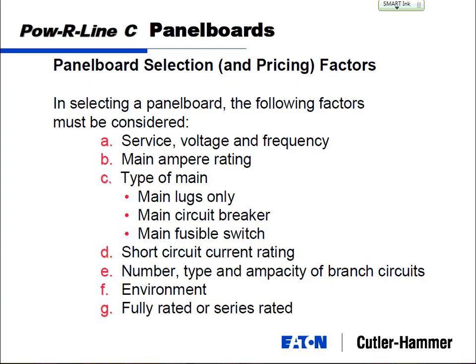For a manufacturer to price a panel board, we're going to need these things to be able to give you the equipment that you're looking for. So this is a good cheat sheet when you get these slides to look at from a manufacturing standpoint. Here's the information that I'm going to ask for if you call me up or drop me an email. The service voltage and frequency. What's the frequency in North America? 60 hertz. I believe it's 50 in Europe, and I don't know if there's anybody who does anything other than 50 or 60.